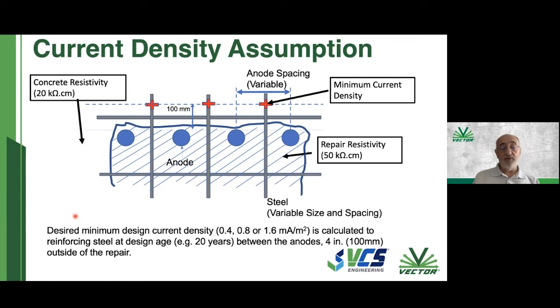In order to do that, we used a model, basically, as I've shown you here on the diagram. That's our model, and obviously you're going to get current delivered from adjacent anodes, and therefore it's the additive amount of current that you get to that point. But the average current density elsewhere over here is going to be much higher, kind of double down here. So if you were aiming for 0.8, you probably get 1.6 down there, and if you take an average, it will be somewhere in between the two. So it's not quite right.